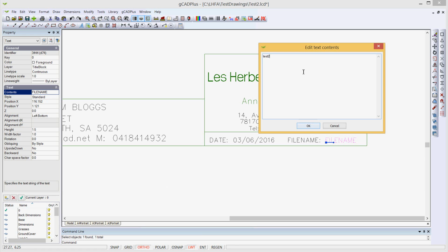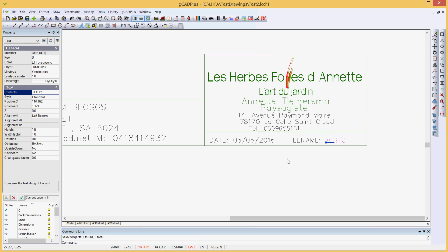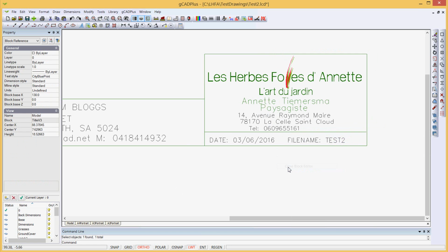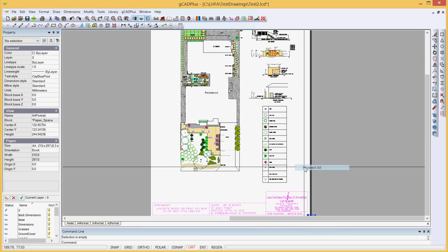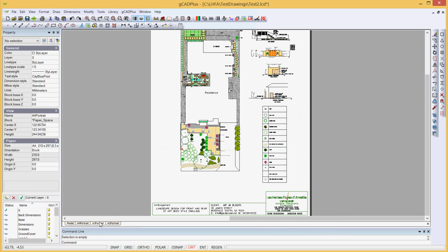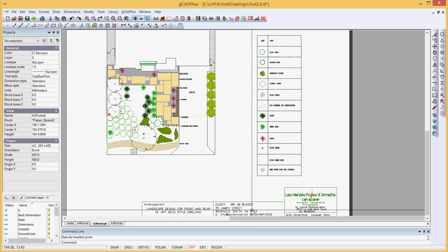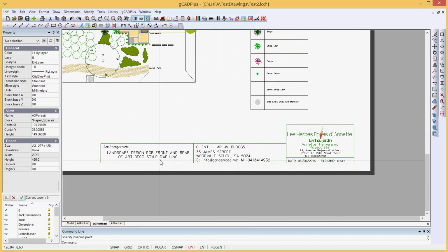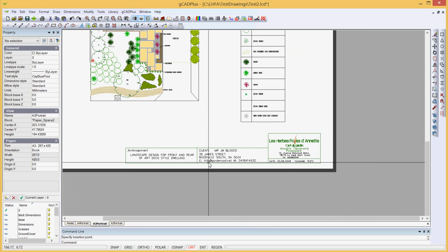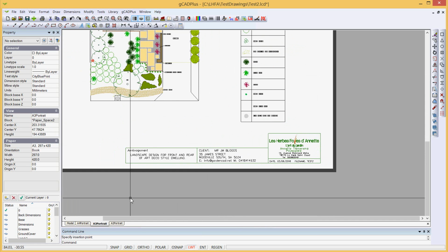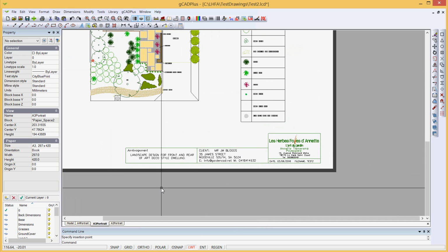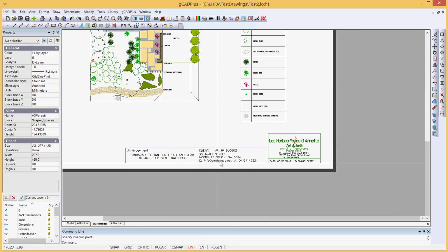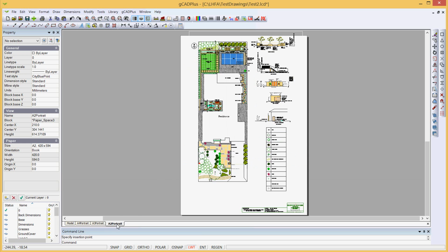And the file name, quite straightforward here. I'm just working on a file called test2. I'll use capitals, I think, because uppercase is easier to read when it's on the drawing sheet. Now we can right click and close the editor and unselect all. If you now look at, well, let's go to the A3 sheet and zoom in here. See that all of the information that's been developed in this drawing is showing there. So editing the one block all the way through updates everything.